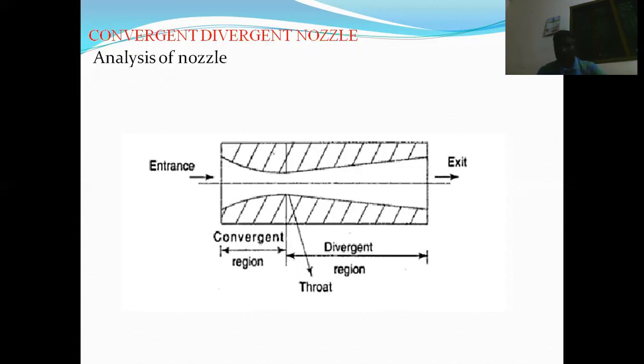When it is going through the nozzle, there is no addition of heat and no removal of heat. That means there is no rejection of heat and no addition of heat. When there is no addition or rejection of heat, it is said to be an adiabatic process, or else a reversible isentropic process. By this thermodynamic analysis, we came to know that the expansion in the nozzle is isentropic. There is no heat loss and no heat gain. We are only converting some amount of heat into kinetic energy.